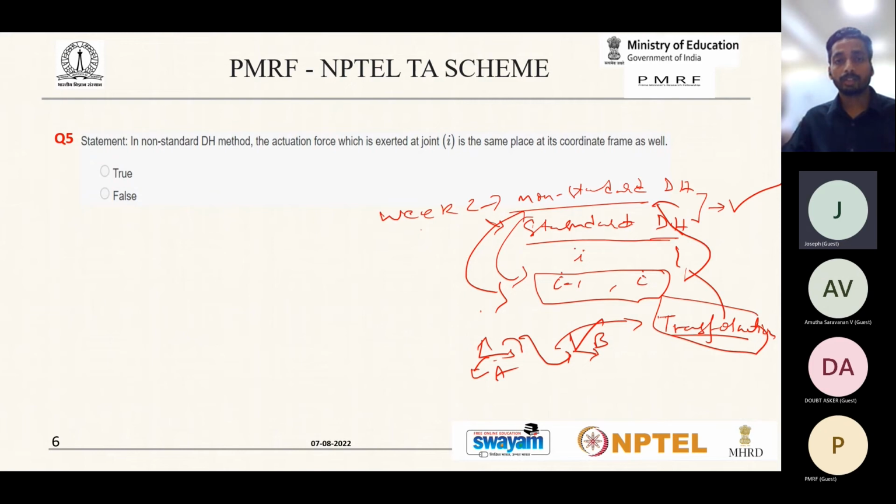So in non-standard DH parameters, the actuation force which is exerted at joint I, they are asking, right? So here suppose this is joint, and suppose this is Z, which is the same place at its coordinate frame as well. Actuation means here if there is a motor, we want to give some torque, so it will try to rotate, exerted at joint I. So this is ZI, and the actuation is also given here itself, the same place as this coordinate frame. And for the sake of simplicity, generally we attach our frame here, right? So the actuation force which is exerted at joint I is the same place as this coordinate frame. So that is correct. So the correct answer for this is the first one, that is true.